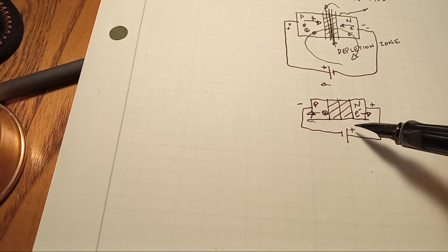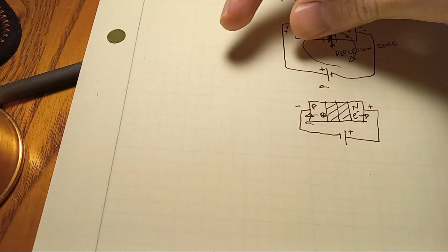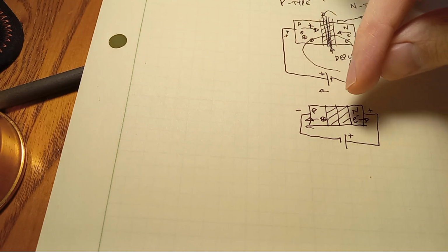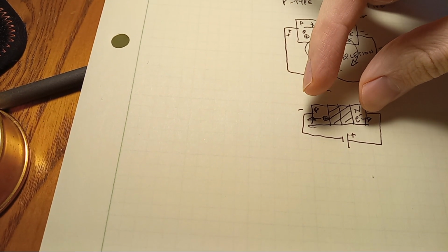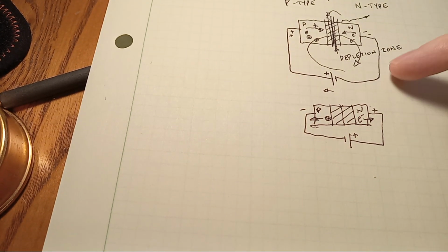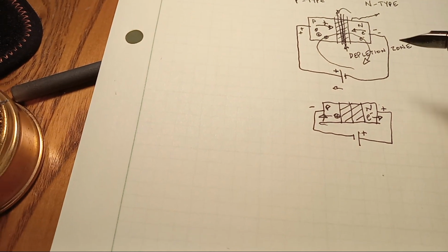The net effect is that applying voltage one way crunches the depletion zone down to a thickness of 0 and allows a current to flow, while the other way, it expands it. It increases the thickness of the non-conductive layer, so the device only conducts current in one direction. There are asterisks. You can force it.